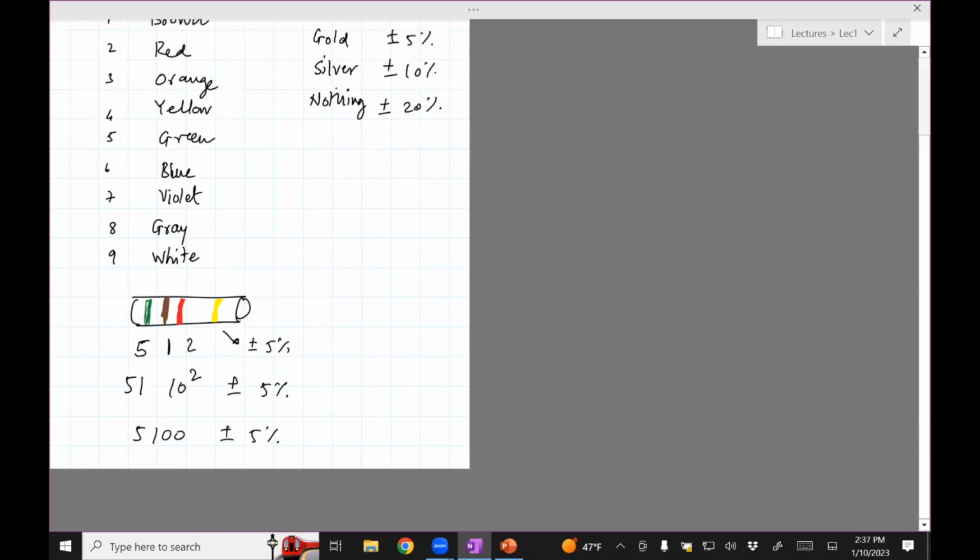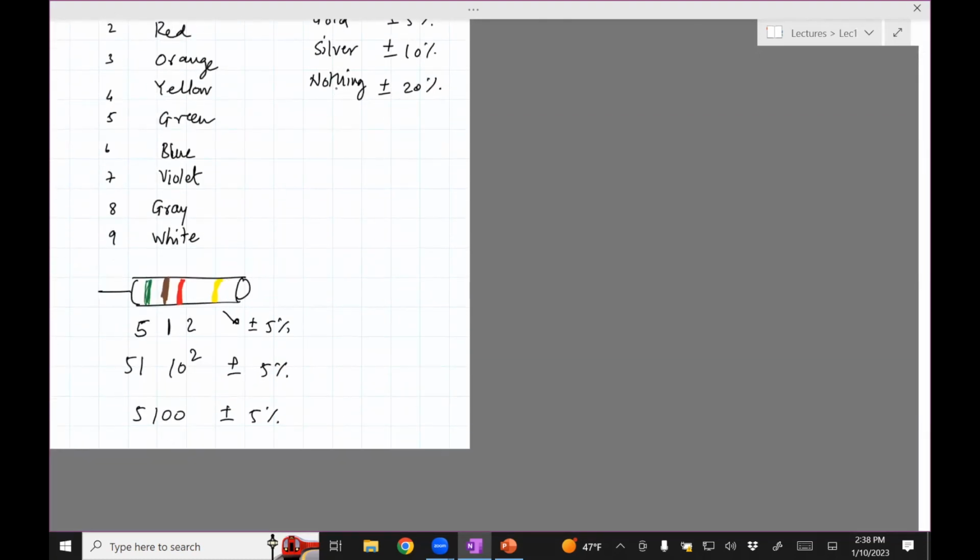Now, this is one way of doing it. The other way is, how will you find the resistance of a resistor? A multimeter has a knob, so you will use a multimeter in lab 2. A multimeter is a device where you can read the voltage or the current. All you need to do is turn it to the resistor knob and connect it to the 2 wires which stick out from the resistor. It'll just tell you the resistance. It's probably faster and more accurate than this way.